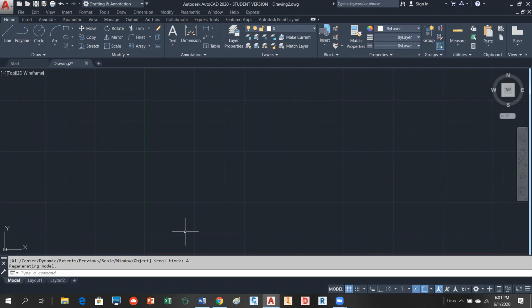So what we're going to do is step around this little sample polygon, utilizing a command called line, which is this guy up here. And we're going to be inputting coordinates in order to do this because we want to get this kind of precise. Because you can eyeball points in AutoCAD, but that's not going to make it very precise.